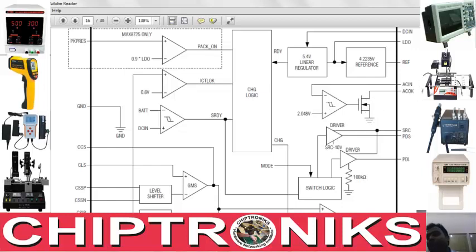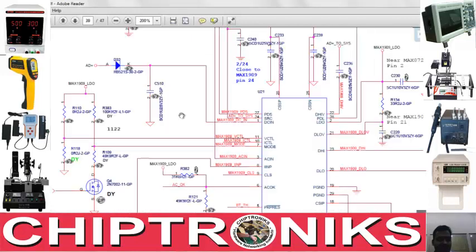So AC OK would be 0 in that case. But if AC in is present, that is, the adapter is present, then this will provide a low value. Low value means the gate voltage would not be connected, and in that case this AC OK would be a high value. And you can see the actual implementation over here.